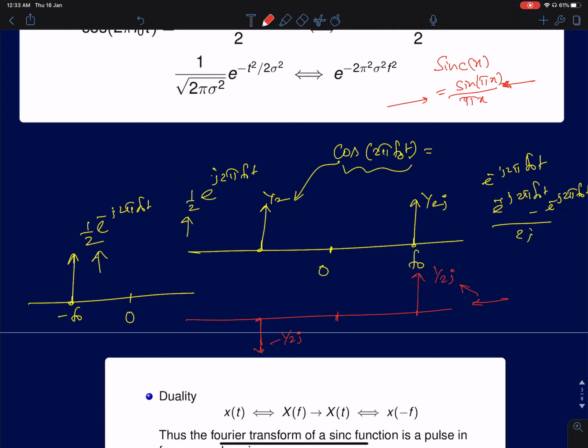And you can very easily see that the positive and negative frequency energies are complex conjugates of each other. That directly comes from the condition that the signal is real itself. The additional constraint that the odd function poses is the Fourier transform being purely imaginary.